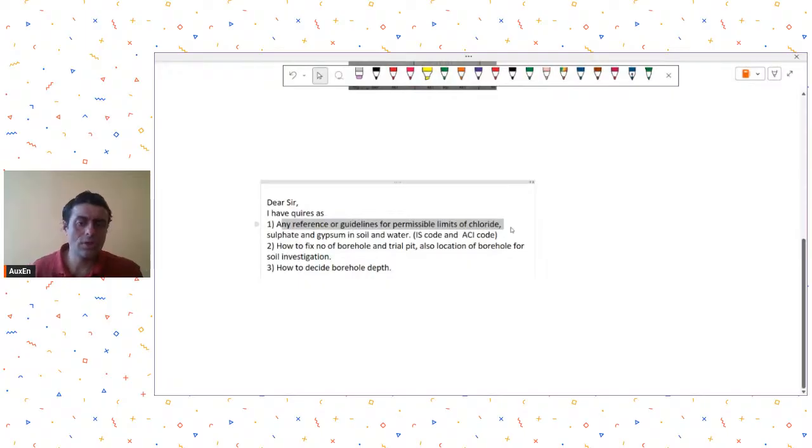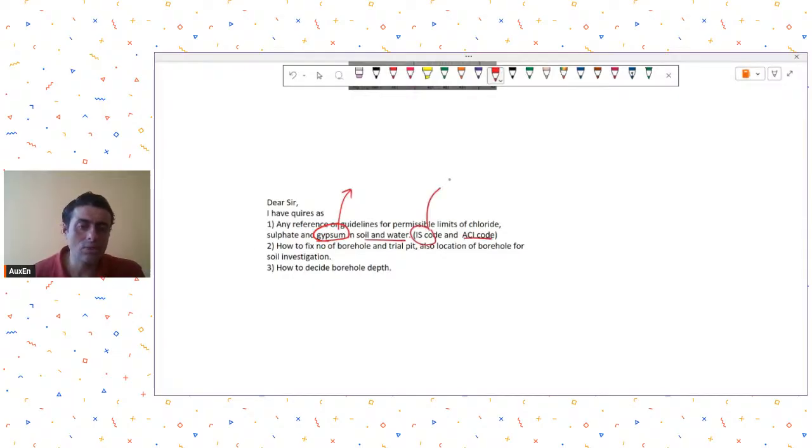He is a working professional, and he has the following queries. Any reference or guidelines for permissible limits of chloride, sulfates, and gypsum in soil and water? About the ACI code, I am not sure at this moment. In the IS code, they have given you the limits of chlorides and sulfates dissolved in soil or soil water. So you can have a look at that. IS 456 gives you those limits.